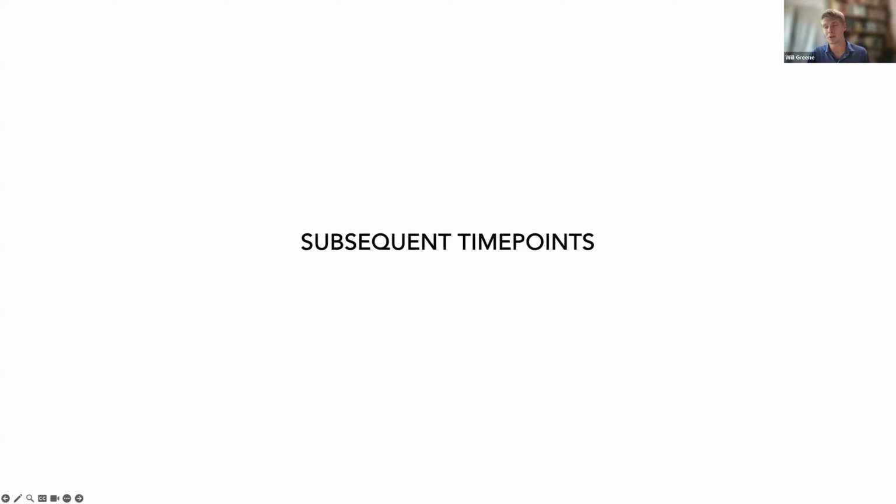Once you've found those corner markers, you need to place at least one scale bar just for consistency. That actually won't be used in the processing, but it's helpful to have just as a check to make sure that everything's working properly. And it's also helpful to use for white balancing because you need to do that each time you photograph a plot because conditions in the water column change over time. Then you just collect your photos.